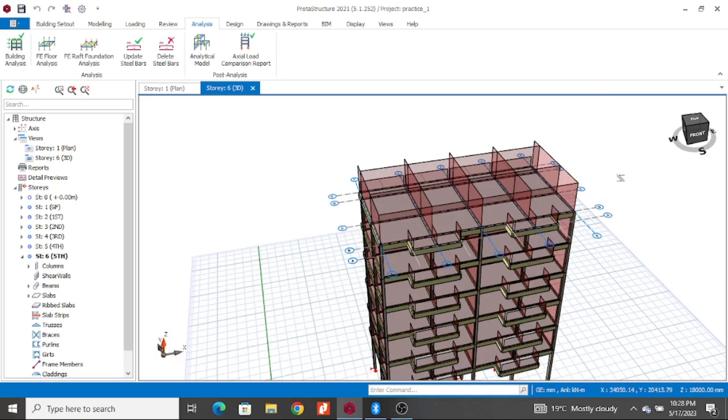And if you have water tanks at the rooftop, it is simple. You just take the height of the tank you are going to place there, and then you multiply by 10. If the height of our tank is 2.4 meters, regardless of the width or the volume of water it's carrying, just take the height multiplied by 10. If it's 2.4 multiplied by 10, that is 24 kilonewtons per meter squared. So that is how we get the live load of the water tanks that are normally on our rooftops.